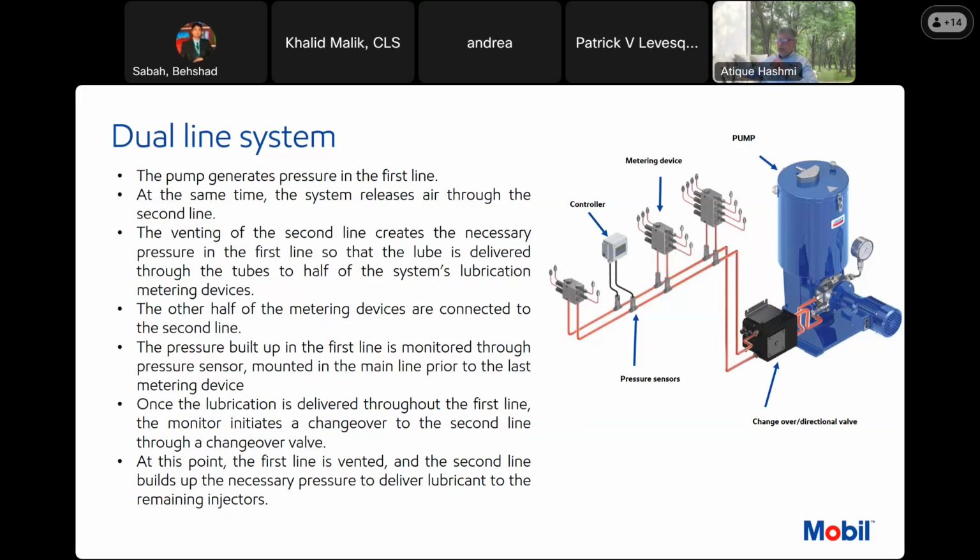In that 100 feet, you would have pipe, fittings, headers, drops, and every connection would reduce the pressure. So for example, if you did not calculate and you dispense a lubricant like 10W30 or 15W40 for 100 feet without considering the pipe diameter, most likely you won't get the required pressure at the end of the line.